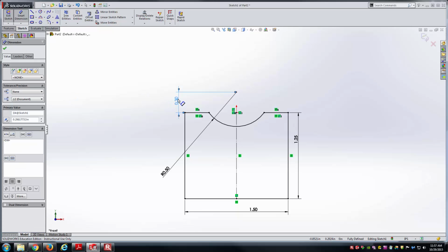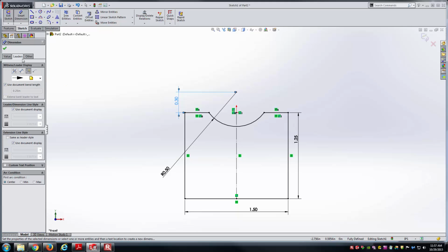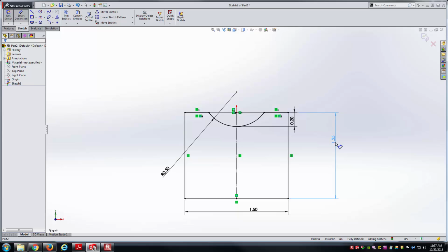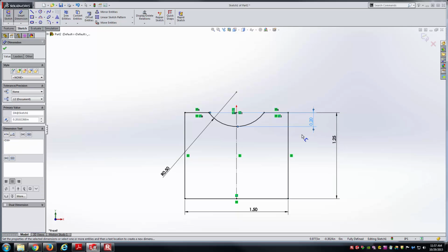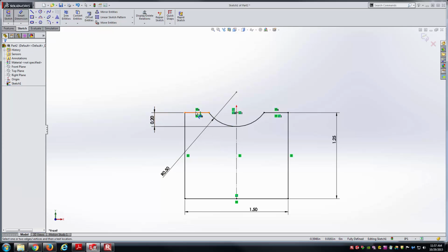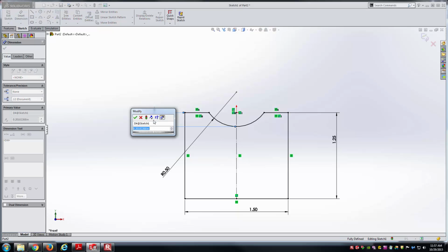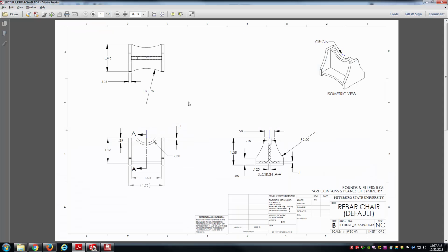With the dimension selected, you go to Leaders, and then under the leaders you'll have Arc Conditions if you have any sort of arc. Here I want the minimum value, which gets me the exact extension line locations I was looking for. I'll pull it onto this side of the part for a little clarity. Now I'm dimensioning between that horizontal line and the very bottom of the arc, and that needs to be 1/4 of an inch, so I'm just adjusting that value.